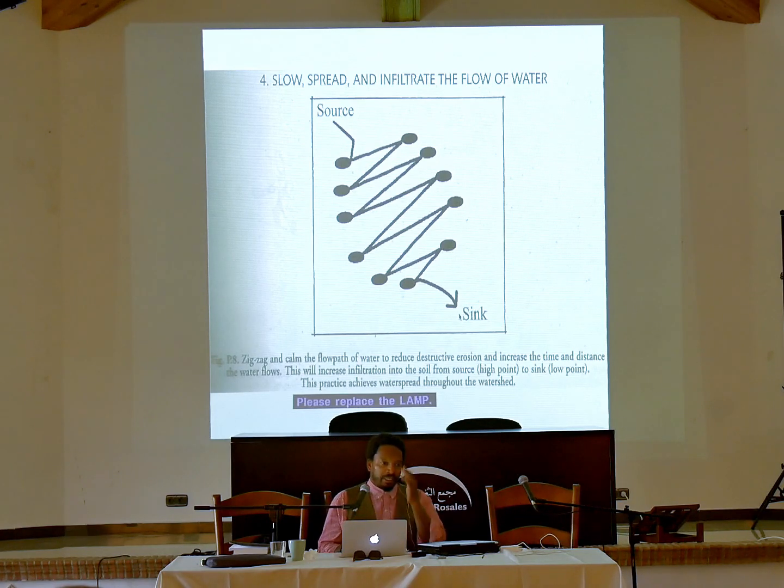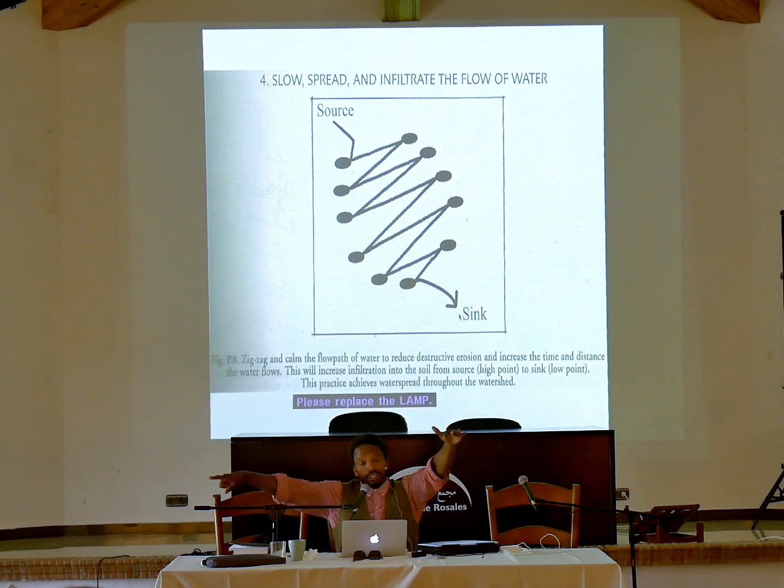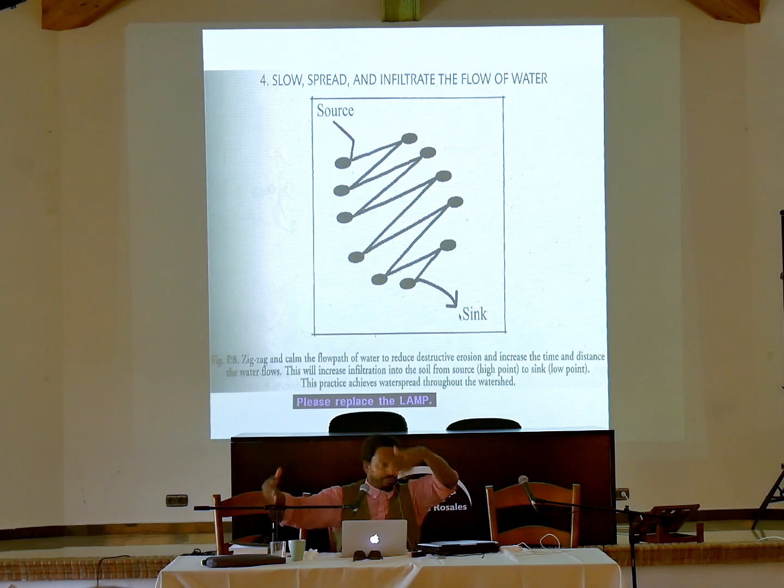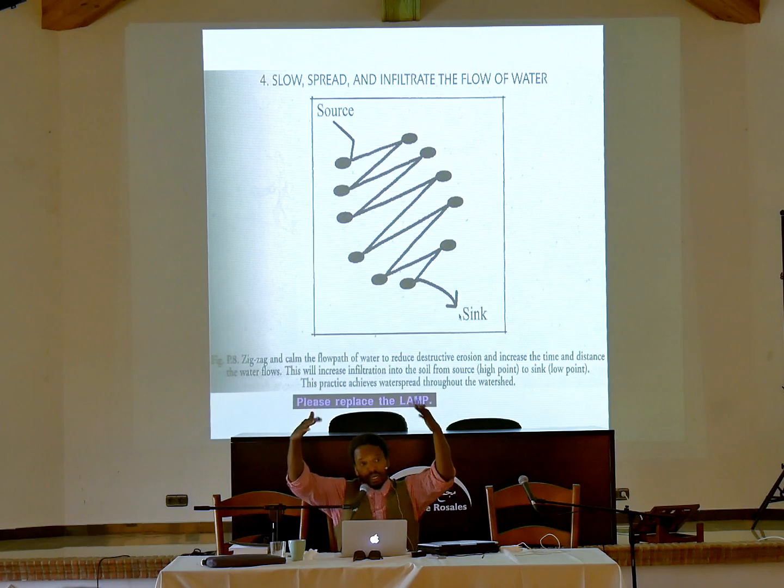It depends on the context, because you might have a part of the land that's on a slope, an area that allows for you to store water up high, and then maybe down low. The strategy would be to infiltrate the water down low, maybe in the flatter, more shallow slopes, because those are likely your primary productive areas. And the reason you want to store water up high is because then you can use gravity to send it down to those lower areas where you would ultimately want to infiltrate the water, to create some kind of growth. So again, they're not working at cross purposes.